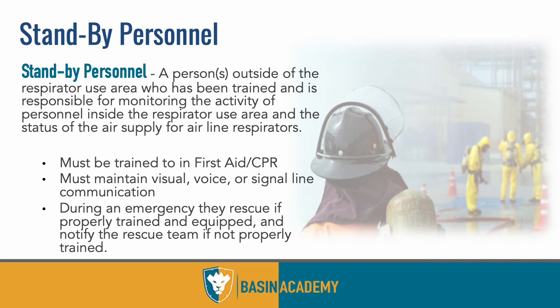So, standby personnel, I mentioned these in brief. This is the guy who's working outside of the red area or the red zone where there are high levels of H₂S. His job is to rescue if somebody were to go down. He's not to be on his phone or doing something else. His job is to be focused on the people working in the H₂S area and be ready, equipped and trained to provide rescue if necessary. This may be done by means of a rope, going in and grabbing them, a winch. There's many different ways to rescue, but this person's job is essentially to be prepared to rescue in the event of an emergency.